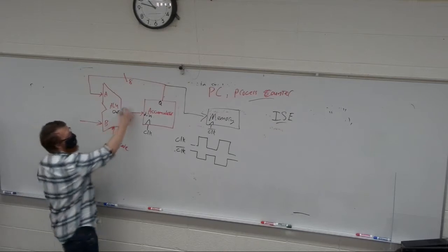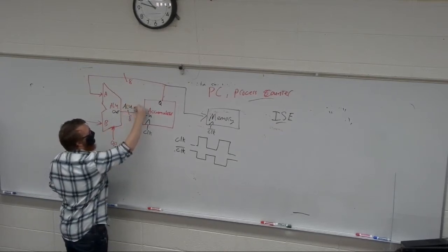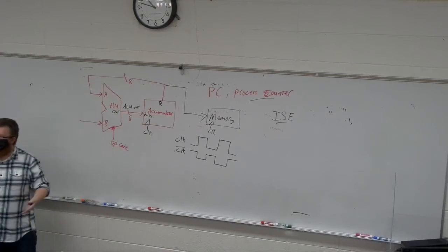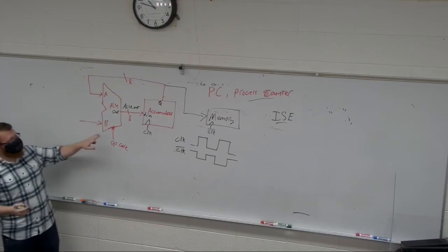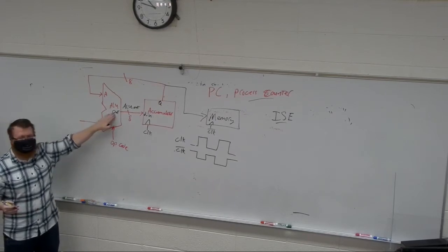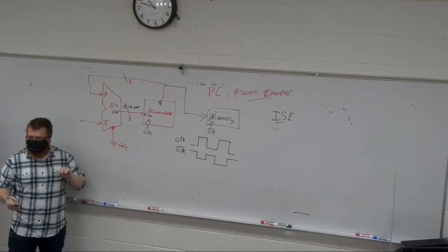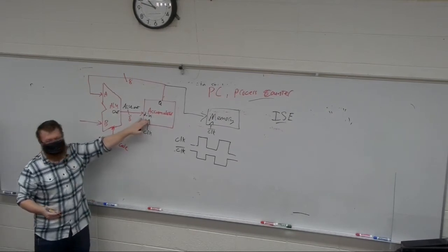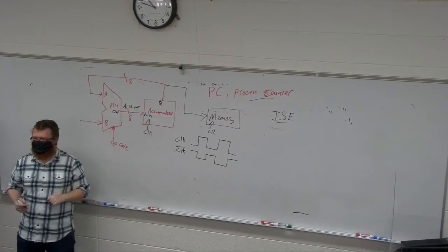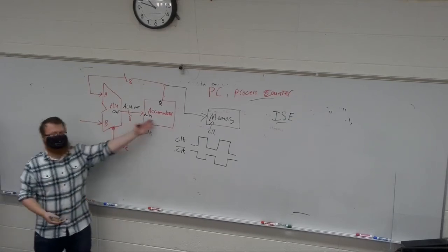Now this signal is going to be called ALU out. And now when I do my port maps, it's clear to me that my port map of out should have ALU out in it, and my D-in port map should have ALU out in it, right? So this is how we use VHDL to connect these blocks.